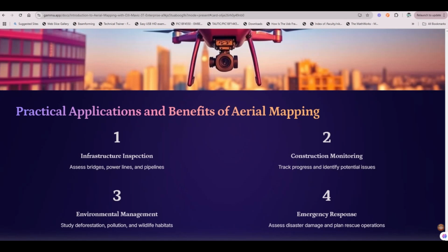So as I mentioned, infrastructure inspection. In electronics communication, they use this drone for communication tower inspection. But one of the things you need to consider is that your communication tower also emits radio wave signals. So if you buy a very cheap low-end drone, whenever it flies there, it goes crazy. But if you get a good drone, it will be able to fly, but it will say there is a signal interference. It will give you a warning.